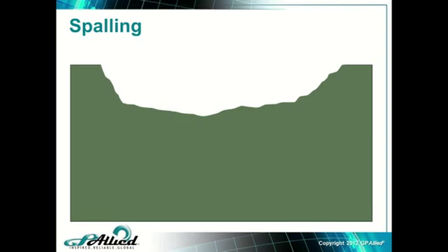Okay, so if we leave that subsurface fatigue long enough, eventually all those little cracks connect, and when they connect, chunks of things start popping out of the race. Now I can feel it with my finger. Now I can hear it when I walk up next to it. And the worse the spalling gets, the easier it is to hear it. The easier it is to feel with the naked hand, you know, if you lay your hand on the bearing. And we call this spalling. So pieces pop out of the surface of the race.